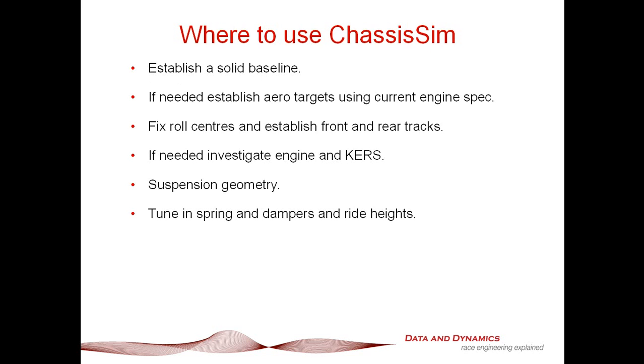Okay, let's talk about the process, about where you use ChassisSim and where it slots in. First things first, you establish a solid baseline. If you don't establish a solid baseline, you're absolutely nuts. And I really cannot ram that point home enough. Then, if needed, you establish your aero targets using your current engine spec. You then fix the roll centers and establish your front and rear tracks. If needed, you investigate your engines and your curves. You move on to your suspension geometry, and then you tune in spring, damper, and ride heights.